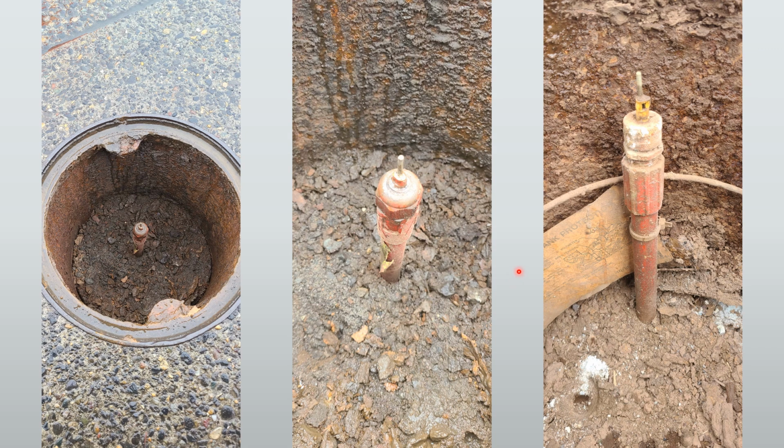This is another alternative test lead method that you may find in the field. So we do see our Type 3 tank little tag hanging out, but this is the structure test lead. I think this is just an older school method, maybe, of doing it. This is just a way to be more of a standalone than using the zip tie method. Just as effective. If anything, it's actually better because it will use its own hole. It'll keep the structure lead away from any risers and possibly a short. Sometimes if an installation crew is a little rough with the wire, you never know, something might get exposed and you might get a contact with the riser and you may have an early failure of your anodes.